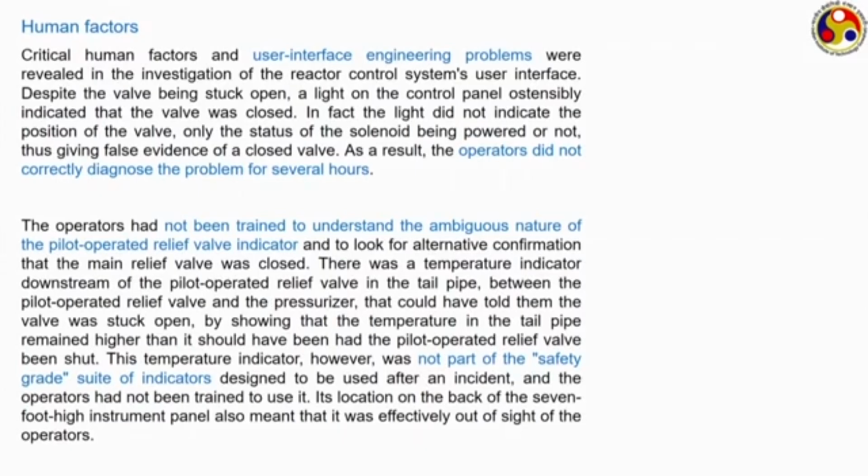The operators probably were not properly trained to understand the ambiguous nature of this pilot operated relief valve indicator, and also they were not properly informed, or they did not have proper experience to look for alternative confirmation that the main relief valve was closed.